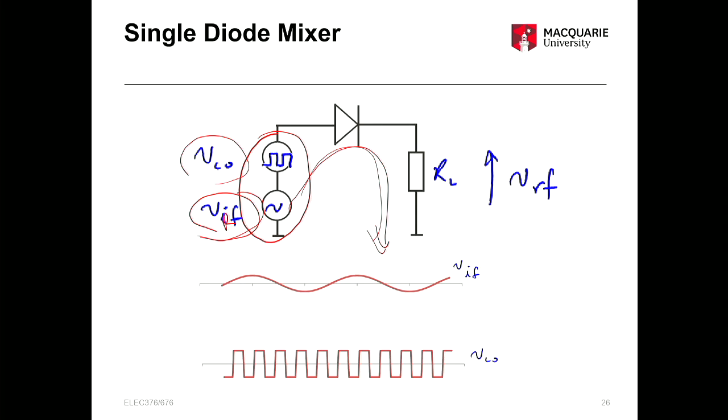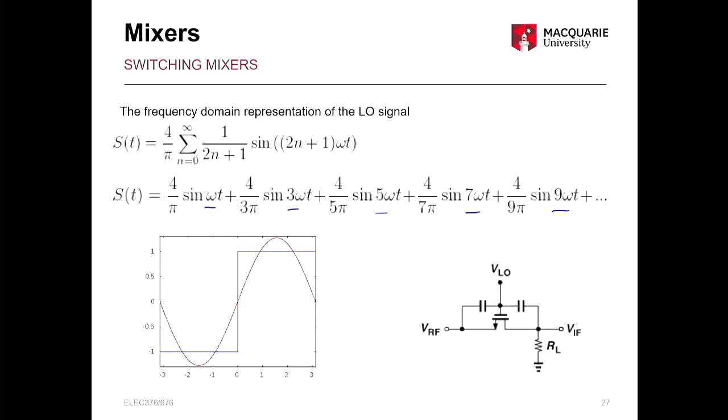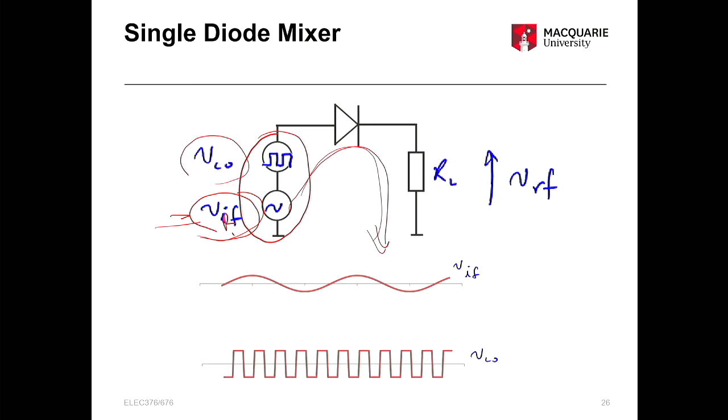Another thing: if you want to broadcast, what you give is the IF frequency. You give your LO here, and finally you broadcast the RF. But on the receiving side, you give RF here, and then you get IF there. So it is interchangeable. Let's look at that.